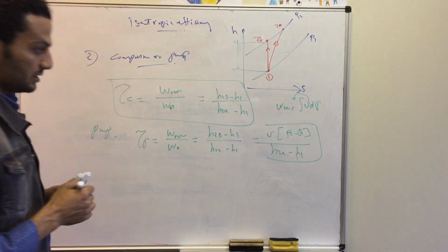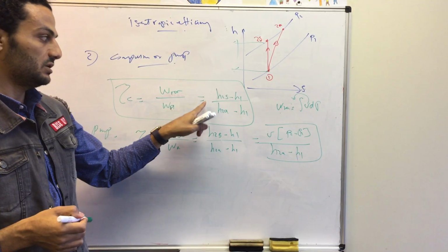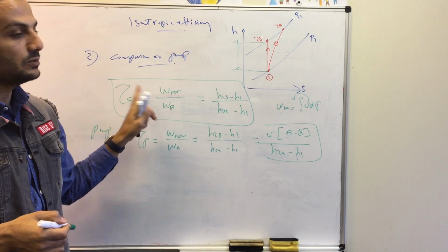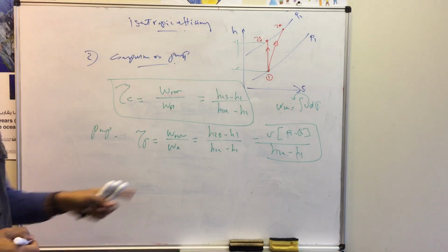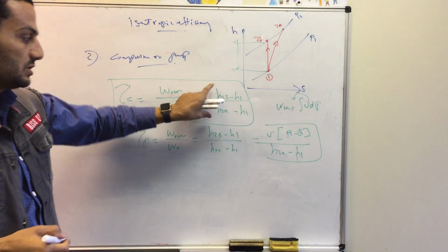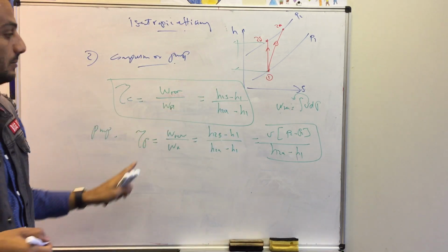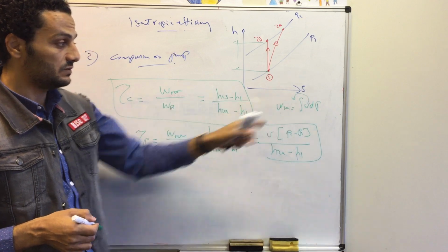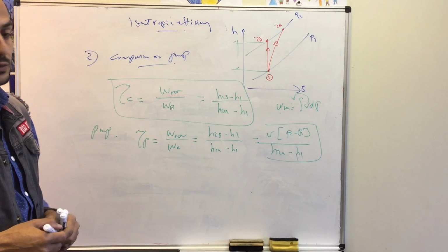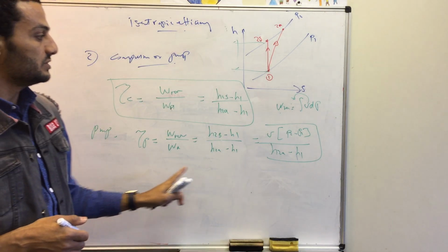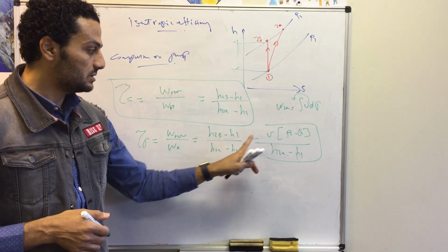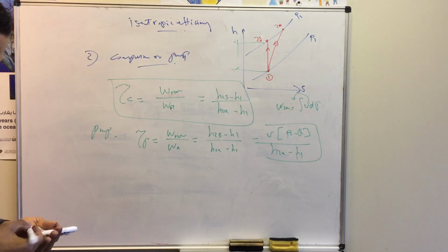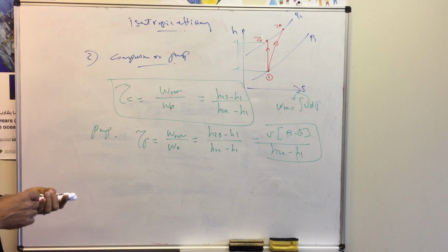So this is only in the case of a pump, but it's not the case for a compressor, because a compressor is dealing with a compressible substance. So we cannot take the volume outside, so I will stick to this relation. But in the case of a pump, we do have the integration of VdP. The specific volume is constant because the pump is dealing with an incompressible fluid. So in this case, h2s minus h1 is the same as v multiplied by P2 minus P1.